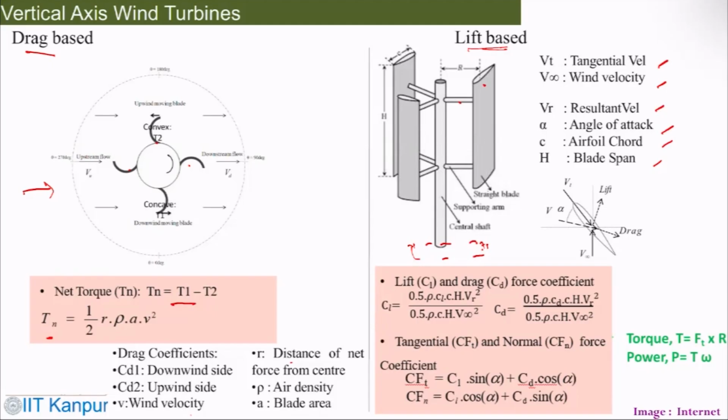So you could easily see the component of the lift and drag forces, and then you have the resultant forces based on angle of attack here. So again, this is your velocity triangle, a similar concept to what we used in the horizontal axis wind turbine. So when the wind is coming, it is with respect to a particular plane of the aerofoil. So you take one aerofoil and see how that looks, but you are looking at it from the top. So this is the cross section.